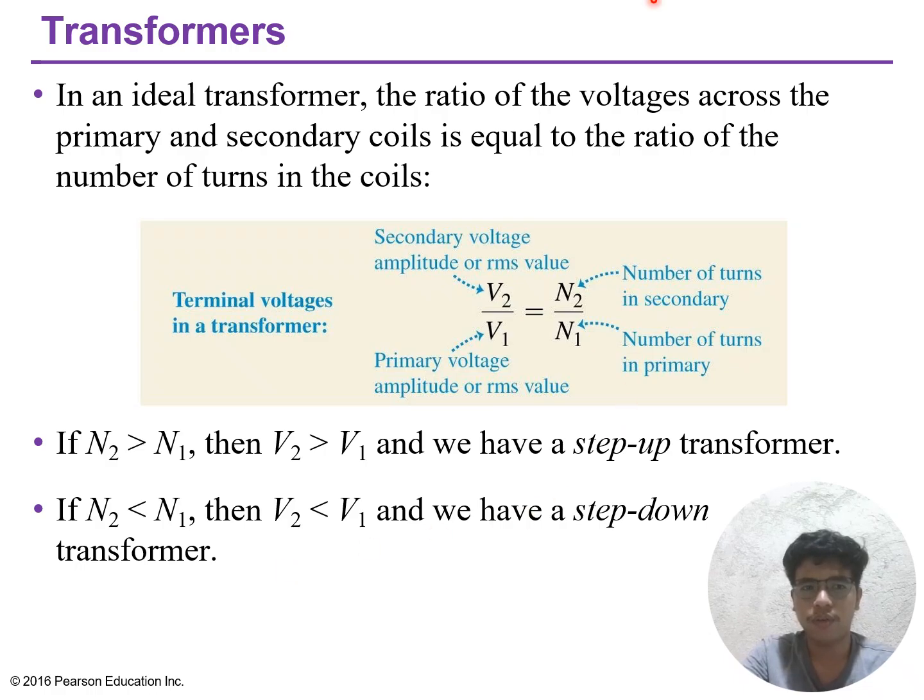This voltage transformation conserves power because P sub 1 equals P sub 2, since V sub 1 I sub 1 approximately equals V sub 2 I sub 2, where I sub 1 and I sub 2 are the primary and secondary currents. The ideal transformer assumption neglects losses like resistance and leakage flux, providing the fundamental design principle for all practical transformers used in power distribution and electronics.